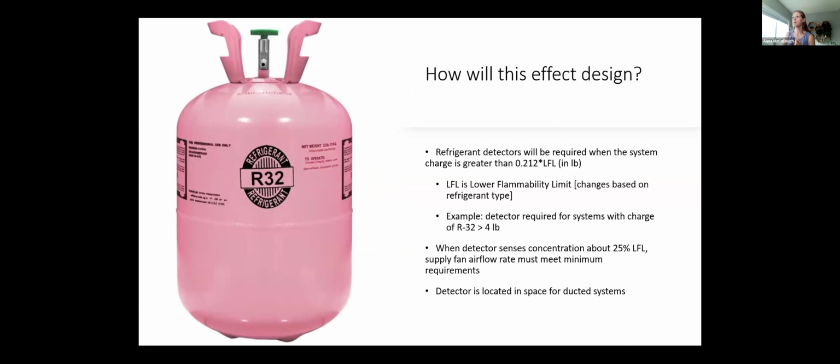Refrigerant detectors will be required when the system charge is greater than 0.212 LFL. LFL is the lower flammability limit. These limits are assigned to different types of refrigerant within ASHRAE and within the IMC. And I believe the LFLs are identical between ASHRAE and the IMC.